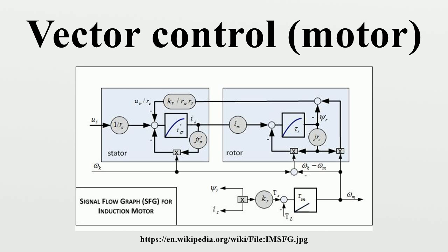Torque and flux can be changed reasonably fast, in less than 5 to 10 milliseconds, by changing the references. The step response has some overshoot if PI control is used. The switching frequency of the transistors is usually constant and set by the modulator. The accuracy of the torque depends on the accuracy of the motor parameters used in the control. Thus, large errors due to, for example, rotor temperature changes often are encountered.